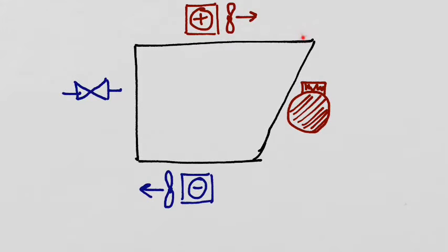Next, the pure vapour refrigerant is passed through the outdoor coil where it exchanges heat energy with the outdoor air. Again, we have a latent process where we see a change in the state of the refrigerant rather than a change in its sensible heat. And when we get to this point here, we have a pure liquid refrigerant, pure condensed refrigerant.